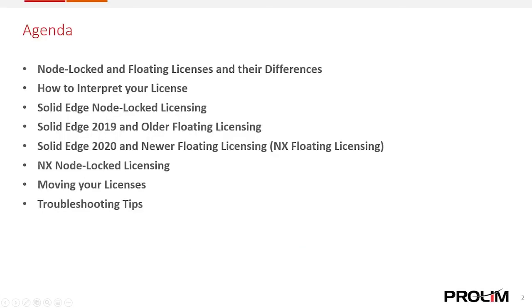Jumping right into our agenda for today, I plan on going through node-locked and floating licenses and what the differences are between the two licensing methods. We're going to go over how you can interpret your license, meaning how you can open it up, read it, and prepare your license file in order to use it for your licensing system, and what kind of information you can gather from your license file.